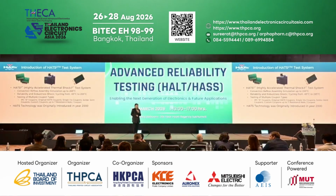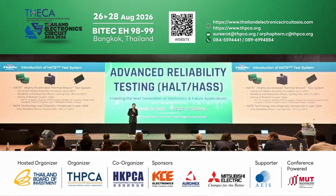The HATS2 system is a convection system. It can test the convection reflow assembly simulation up to 265. It can also test the reliability and robustness shock cycling from -65 to 265. It can also test multiple types of coupons. We can typically test IPCD coupons, original HATS coupons, single via coupons, solder joint coupons, and custom coupons up to 7 resistance nets per coupon.